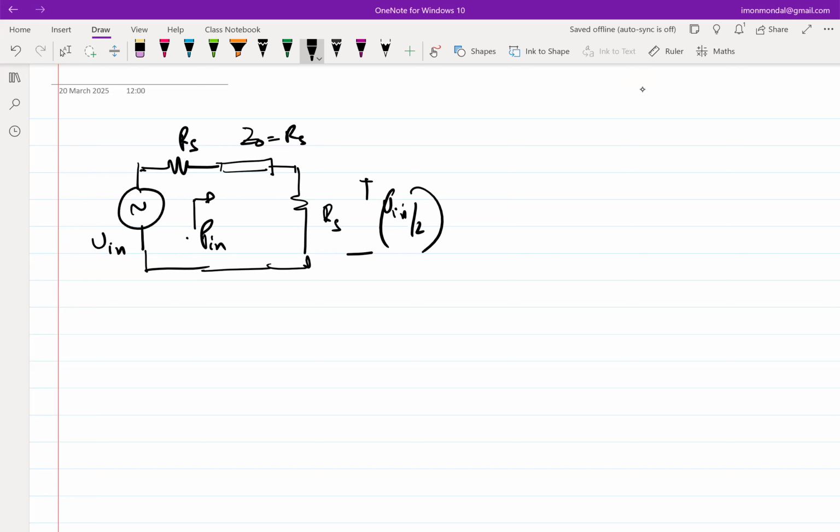Yeah, right. So ultimately here I know that there's no reflection. I can basically find out the voltages at any point. Whatever goes in, V squared divided by R. The P in is essentially the power, right? So your P in is essentially V in squared by RS or 2 RS, depending upon whether you are taking the amplitude or RMS, right? So if I take RMS, this becomes V in squared by RS. Right, V in squared by 4 RS, sorry, because this is V in by 2.